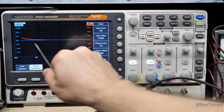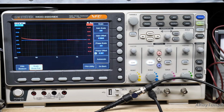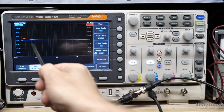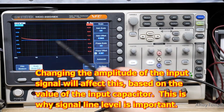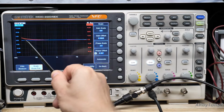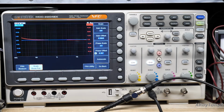So what this tells us is there is a little bit of phase shift, and that's partially because if you look at the schematic of that buffer preamp or buffer amplifier, you'll see that this does have some coupling capacitors in it, and you're looking at the effect of that capacitor. So we may be able to adjust that a little bit and get it to be flat at low end, but that's clear down at the 10 hertz range, and it's only shifting it a tiny little bit. And by the time you're at 20 hertz, you're down by maybe 2 degrees or 1 degree, so it's hardly anything at all. Very low scale. All right,